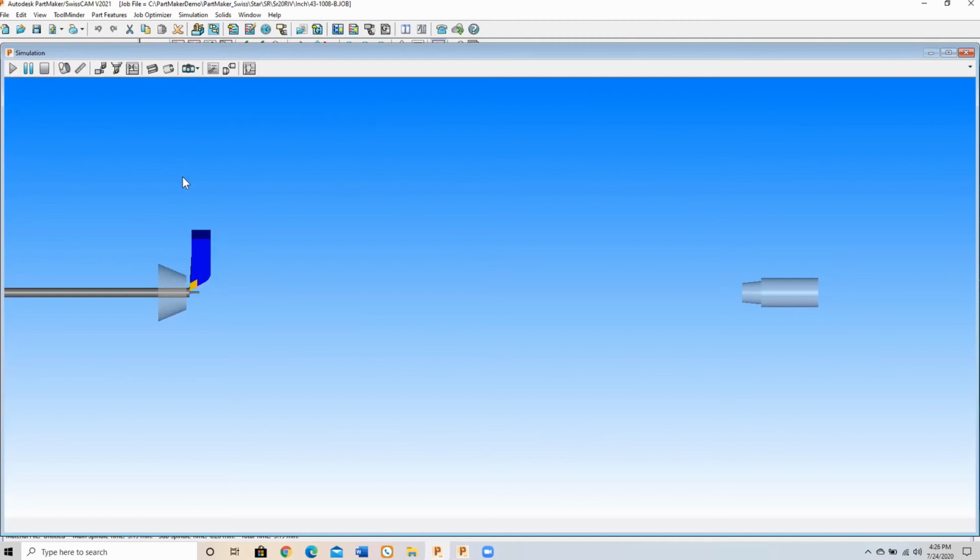And we'll start by cutting on the main spindle. Now the process is always to run the main spindle first and then transfer to the sub spindle. Once that's done, you'll see both tools working at the same time. All this work that we're doing on the sub side is considered to be, put it in quotes, free work. And the reason we call it free work is because while the main spindle is working there, we're getting the sub spindle to work here. So we're saving all the time captured on the sub spindle and using it while the main spindle is running.